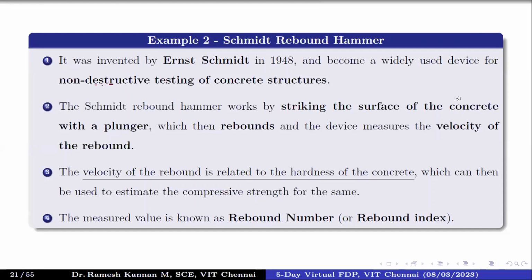It basically works by hitting the surface, and by the velocity of the rebound, it will return a number called the rebound number. Based on that, we will use a graph to understand the compressive strength and so on, right? And some refer to the rebound number as the rebound index also.